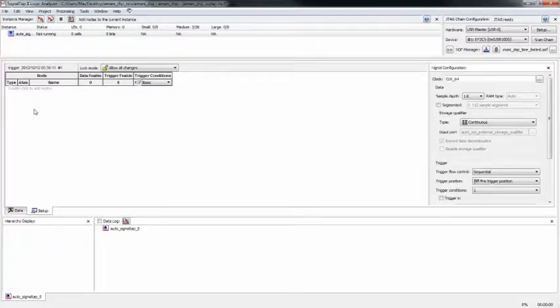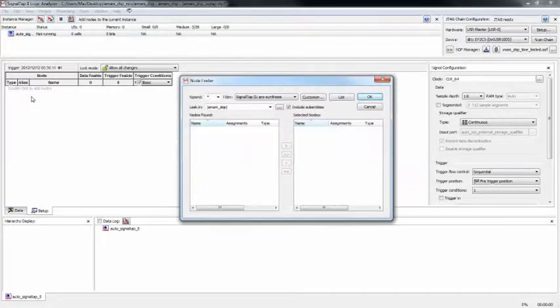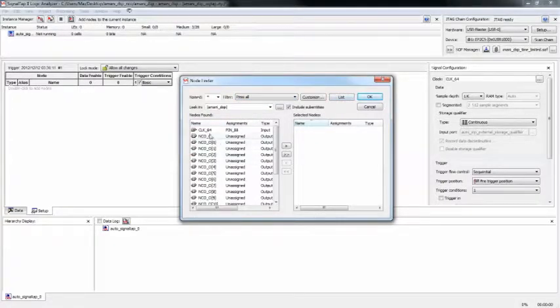So basically we want to bring up the signals that we want to monitor. You double click to add the nodes. Again, let's just use Pins: all list. You cannot monitor the clock because that's what's being used to trigger the nodes. So in this particular case, the only one to monitor now is the NCO_out.